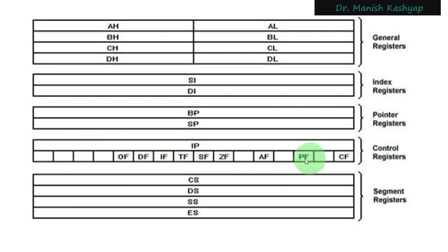You can call this a flag register, or you can call this program status word, right? In 8085, program status word was a combination of accumulator as well as the flag register. Here it is not the case. Here the flag register itself is called the program status word, or PSW. And PSW is accessible to the user by this command called PSW. We will see it when we study the instruction set of 8086 in complete detail. So these are the details of this programming model that is available to the user for programming the 8086.